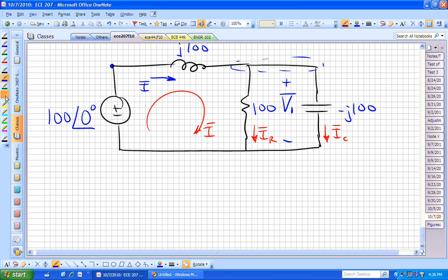Those are good questions. I'm being a little bit quick in saying, oh, there's only one node. There's really more nodes than one, but there's one that we really want to find, is maybe a better way of saying it. If we write KCL at that node, now you can forget that blue I, because I maybe want to look at all of the currents going out of that node and sum those and set those equal to 0.